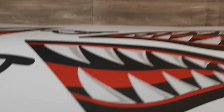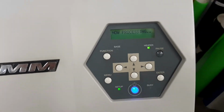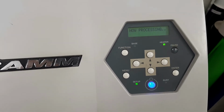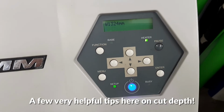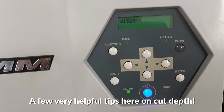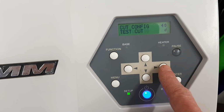So guys, I've just loaded the print up into the printer, and I'm going to do the contour cut now, but there's just a few things I want to show you here, which is really handy, and I use this every single time I put a piece of material in here that needs to be cut. So of course the depth of your blade needs to be correct. If it goes too deep and it cuts into the backing paper, when you try to weed away your graphic, you'll have all sorts of issues. So you need to get the depth right so that it goes through your graphic and not through the backing paper. So go into function, go down to cut configuration, go over.